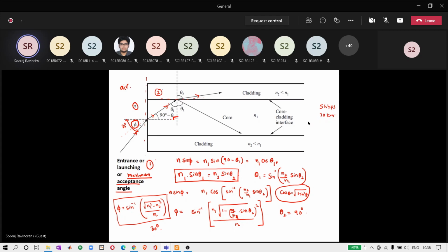The reason the distance between the transmitter and the receiver cannot be made very large, even though the optical fiber has a small loss, is that whenever you lay optical fiber, you cannot always lay it as a perfect straight line. There will always be some bends, and all those bends are going to cause some losses. So we'll study those bending losses in optical fiber.